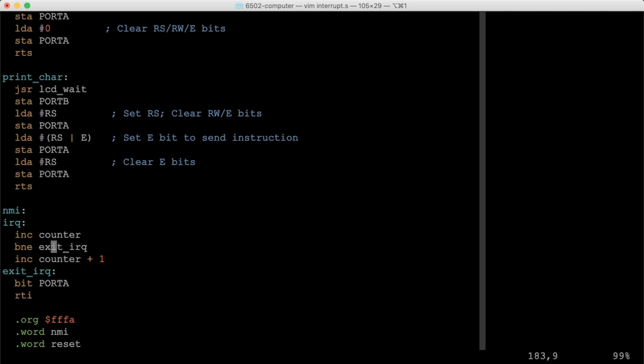So the interrupt is triggered, we increment our counter, and the problem is that we reset the interrupt so that if the switch continues to bounce, we're going to get further interrupts. But if we put a delay in here, then we increment our counter, the interrupt is still asserted, and we're still in the interrupt handler routine. If we sit around for a little bit of a delay, then any switch bouncing would presumably happen during that delay period. Then we reset the interrupt and return from the interrupt handler. Hopefully in that case, we won't get that bouncing.